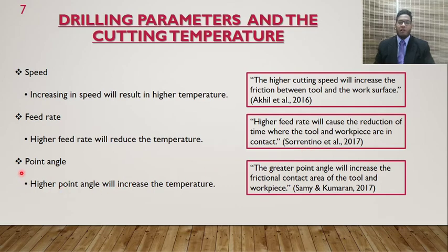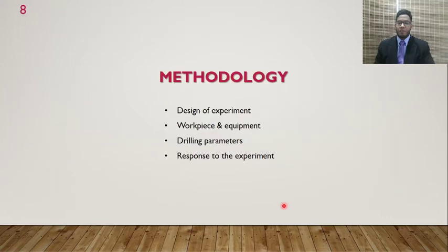Lastly, the point angle. A higher point angle will increase the temperature. This is because a greater point angle will increase the frictional contact area of the tool and the workpiece. So, this is the methodology of this project.